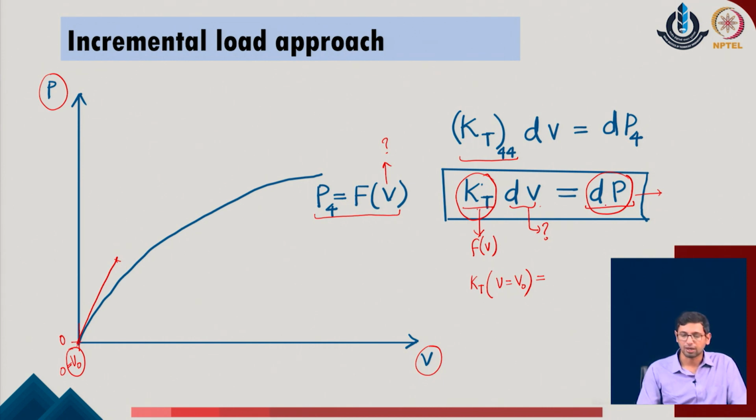With this point in mind, we define our first increment in the system and we call it, say, d of p1 in the given problem. As I define d of p1, my load value from the initial value which I say as p0 changes, and I increase this value by this magnitude which is d of p1. As I increase the load by d of p1, the corresponding displacement can be evaluated with respect to the constant value of the kT stiffness which I have obtained.